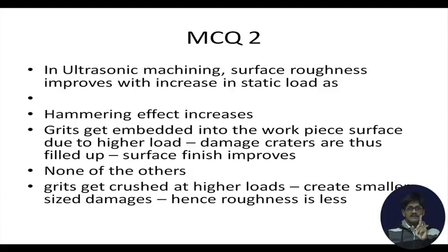Actually, grits get crushed at higher loads, and therefore they are rendered into smaller grits, and these smaller grits give rise in turn to lower values of roughness, and surface finish improves. But you are going to lose in MRR. MRR is going to come down.